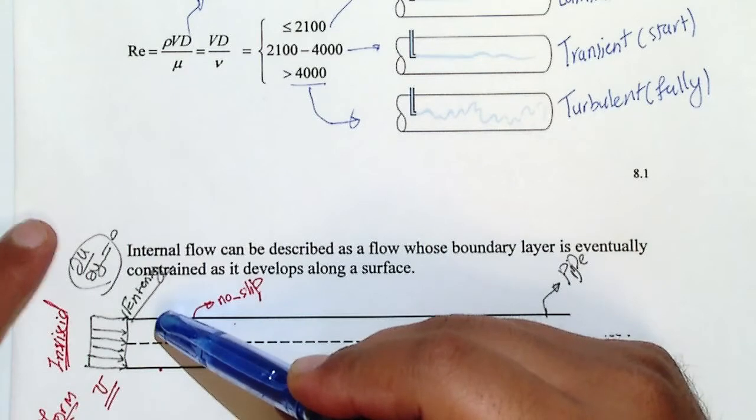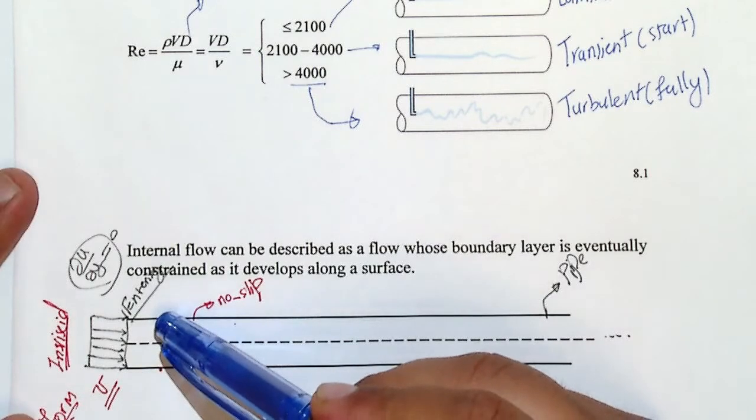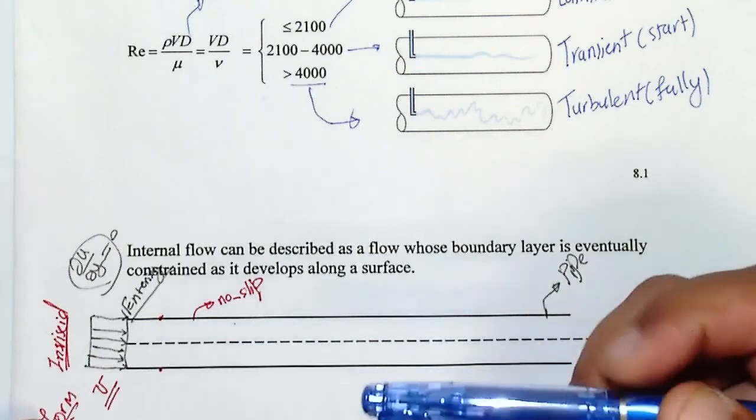It means that it sticks here, and because of sticking to the wall, the next layer shows that there's a friction between the layers, but it's moving toward the center. The layer close to the wall is going to stop, and then it stops the next layer close to it or decreases its velocity, and that also is going to stop or decrease the velocity of the next layer after that, and the next layer after that. But it takes time for the effect of the no slip boundary condition to reach the center, right? So that's why.